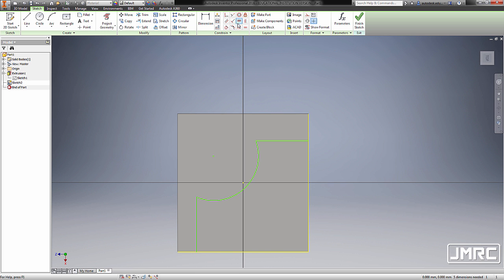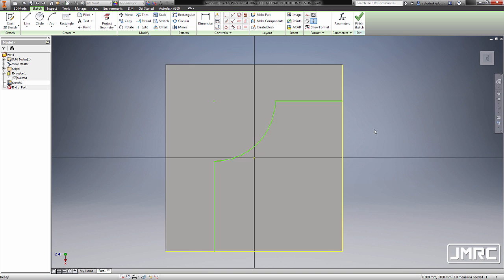I'm going to head to constraints, selecting horizontal, selecting our center point. So notice when I hover my mouse over our center point, we are given a yellow dotted line, meaning the effect would be vertical. So selecting our center point and this end point. Next, selecting vertical constraint, selecting the center point and this end point. Hitting escape. Grabbing our dimension by hitting letter D.